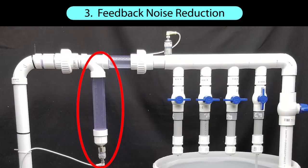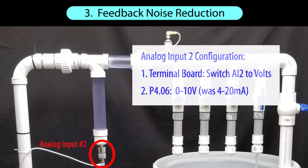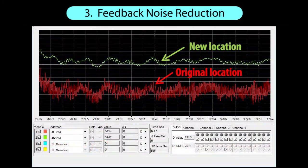By adding a stub pipe like this, you can get the sensor out of the main flow so it's not getting beat to death by the water. I wired the second sensor to analog input 2 so we can compare it side by side. For the record, I had to switch the terminal board switch for analog input 2 to volts, and I set up analog input 2's parameters like this. And look how much the noise is reduced simply by putting the sensor in a better location.